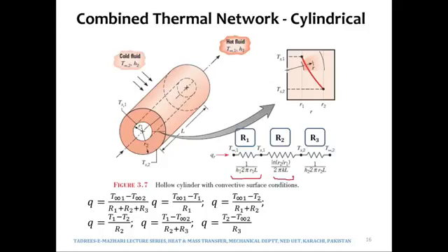So now the heat will reach. The inside convection is taking place between T infinity 1, the steam at, for example, T infinity 1, and the inner surface of the pipe, which is at T1 or TS1. Now the outer surface of the pipe is at a temperature of TS2. Therefore this conductive resistance would be between the nodes at which the temperatures would be TS1 and TS2.